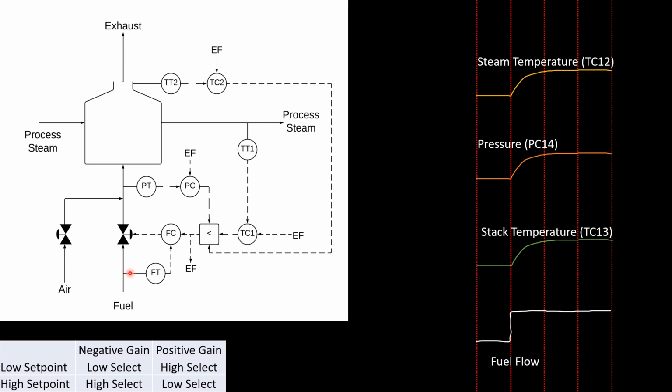And then with a heater or furnace or a boiler, anything that you have a combustion reaction, a fuel air mixture in order to have heat transfer into some sort of process fluid, you would have this be ratio controlled, fuel and air together, to make sure that you have the right mixture, not lean, actually rich in oxygen, for safety reasons.